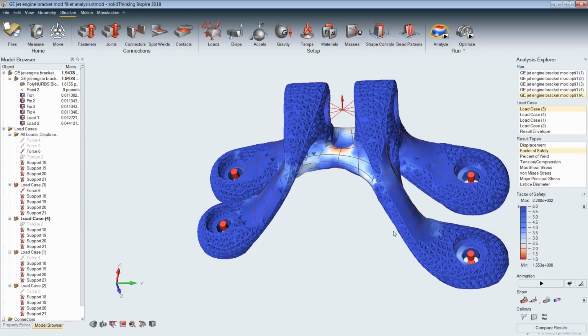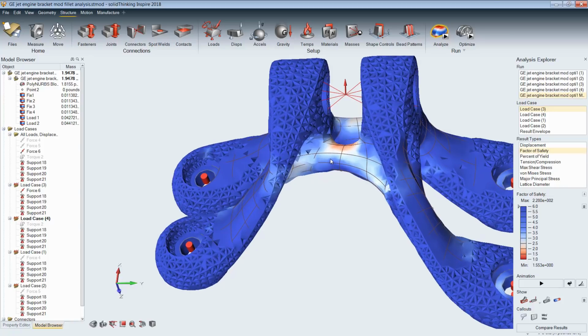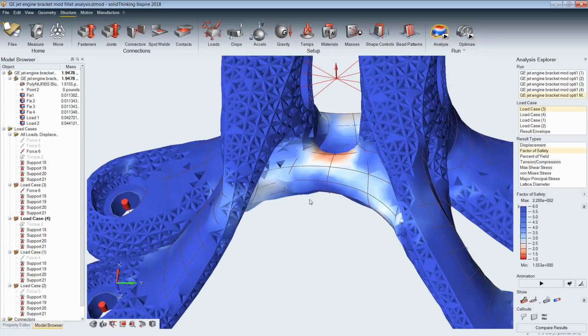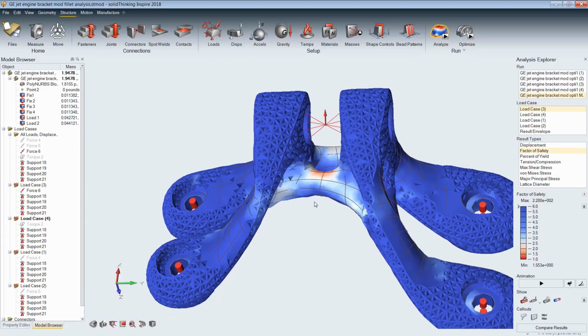Like any FEA program, this is the entire FEA results that you're looking at. Once again, we did not request 100% lattice, and hence there are regions here that have relatively higher stress, where it's kept the entire solid model and not removed material. Whereas there are other regions where the stresses are relatively low, where it's tried to remove as much material as possible.